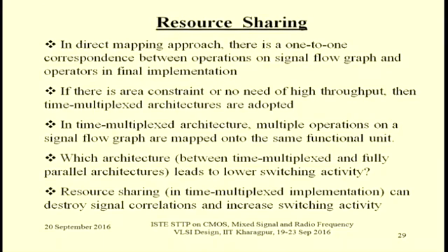So which architecture will we go for? This is very interesting. If we can afford to spend much for duplication of elements, or say parallel operations instead of time multiplexed architecture, do we gain in power? That is the question. Will we have lower switching activity? Yes or no? Resource sharing in time multiplex implementation can destroy signal correlations and increase switching activity.